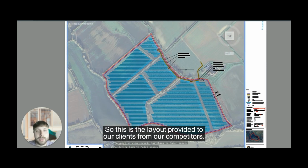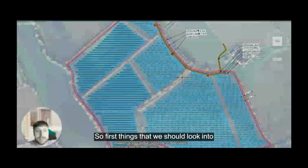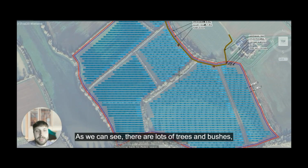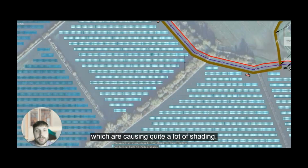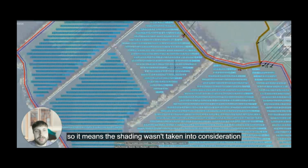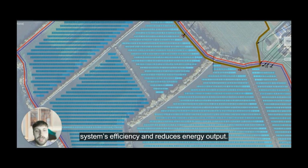So this is the layout provided to our clients by our competitors. As we can see at first sight, it may seem like a normal layout, but let's analyze it step by step. The first thing we should look into is the obstacles within the boundaries. As we can see, there are lots of trees and bushes, even inside and outside, which are causing quite a lot of shading. And this shading is going over the modules, so it means the shading wasn't taken into consideration, which is a huge problem because it significantly affects the system's efficiency and reduces energy output.